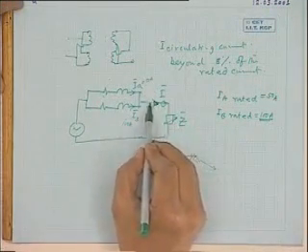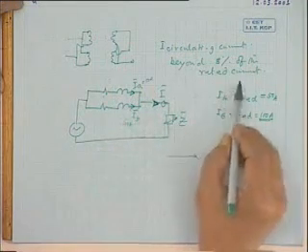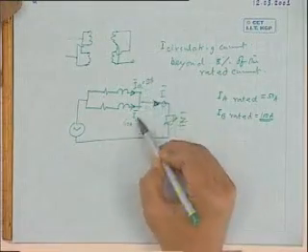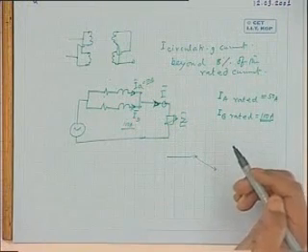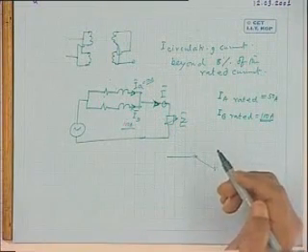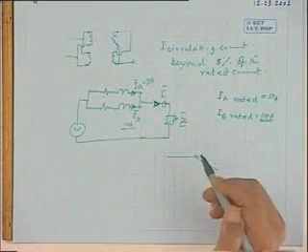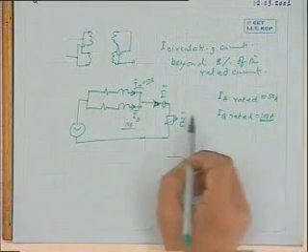In order to get 150 ampere at the output, the currents in the phases, in this particular case, when the impedances are inversely proportional, these two transformers will then become slightly overloaded. Are you getting? That point must be borne in mind. Is that clear to everybody?